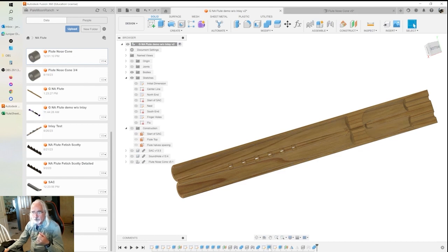So I'm going to go turn off the holes. I'm going to do a suppress features on that extrusion, suppress the holes. I'm going to do the same thing for this. I'm going to go to the extrusion for the flue, and I'm going to suppress features there. And now I've got a picture of what I want on here. And because the mirror that I've chosen here is the side-by-side, it also disabled the cone on the end, which is fine. We'll cut that out when we do the top and the bottom as well. We don't want it to cut those in quite yet.